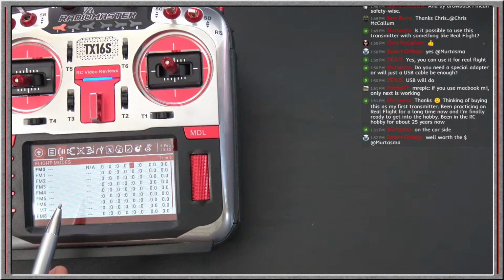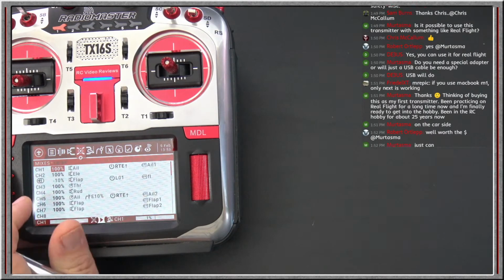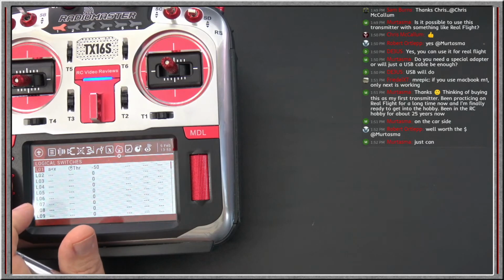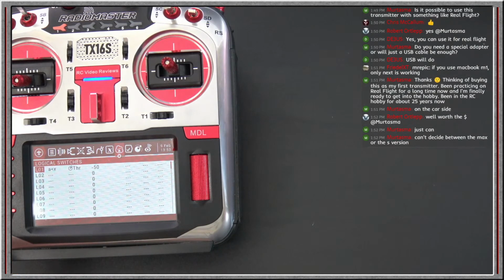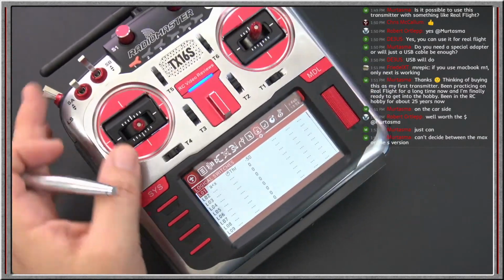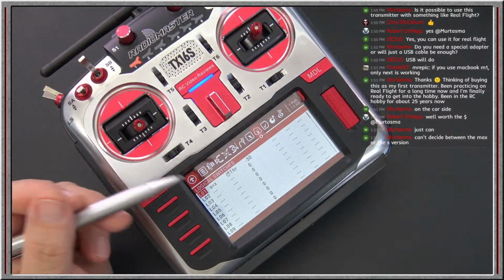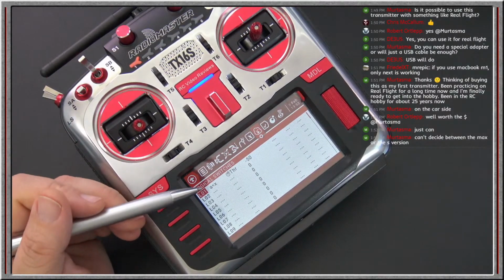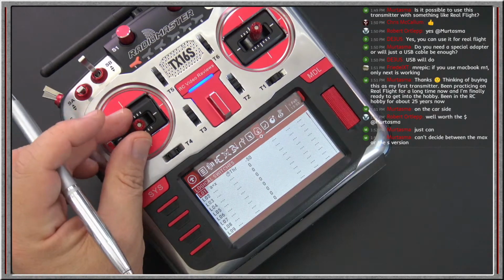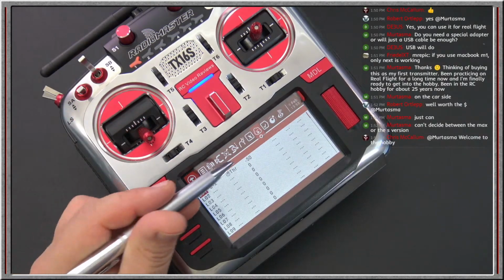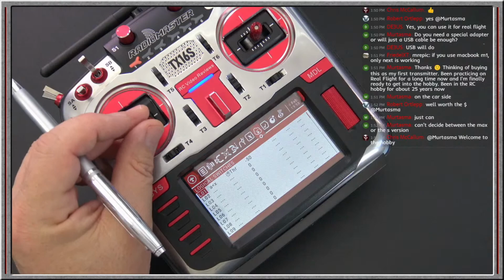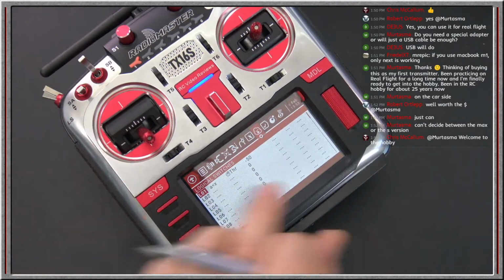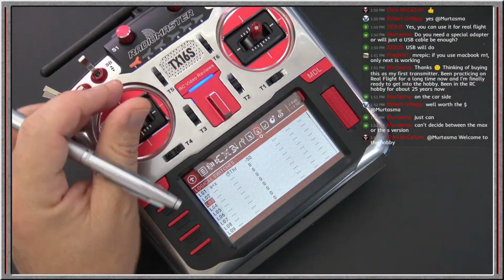Any drawback, safety? No. Logical switches, no. There's no drawback to using logical switches, as long as you understand the logic. If your logic's wrong, then you can create a problem. I mean, it's pretty easy to say that's down. In a logical switch, you have to know what would cause that switch to go active. I know in my case what causes it to go active, and that's when my throttle is below 75%. So I know when it's below 75%, L01 is going to go live.